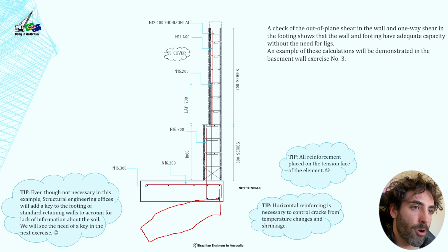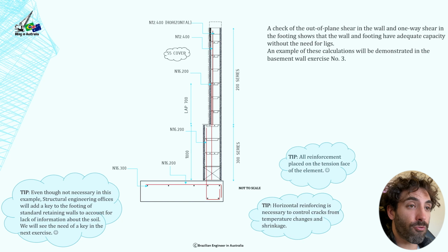That's a terrible drawing, I know, but anyway, the footing is trying to do this, look. So we've got tension on the top face, that's why we have reinforcement at the top of the footing.